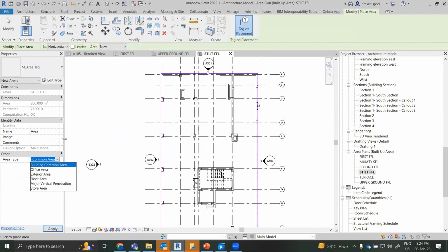Now, if I talk about rentable area, your wall thickness will be included, right? It is not the carpet area, it is the full floor area, so you can actually segregate. For rentable area, in terms of foreign standards, everything is included except your openings, except your shafts and all, right? The thickness of the interior walls is also included. If you are creating carpet area, you can just go for the room calculation, right?